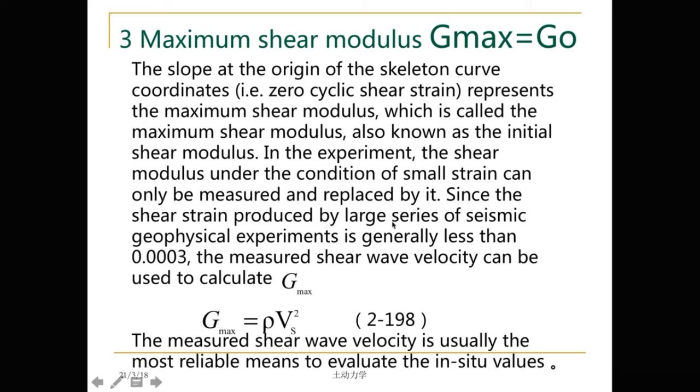You see, here it is said that the seismic geophysical tests are under the condition of very small strain. Then for backbone curves, this is very close to the original point. Then we can use the seismic geophysical test to get the maximum shear modulus or initial shear modulus.